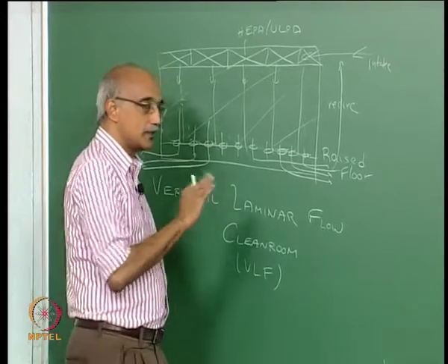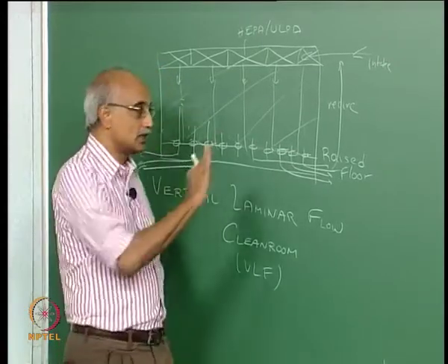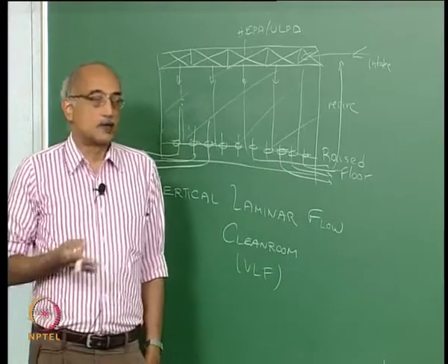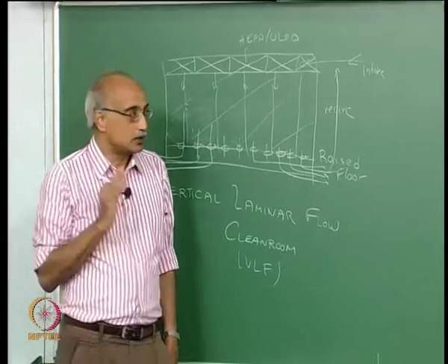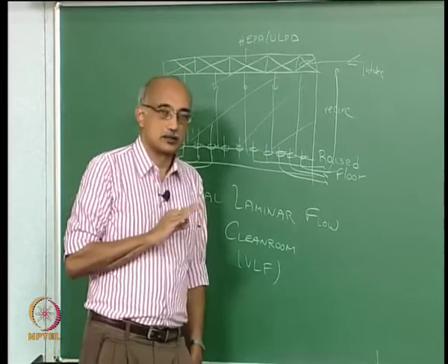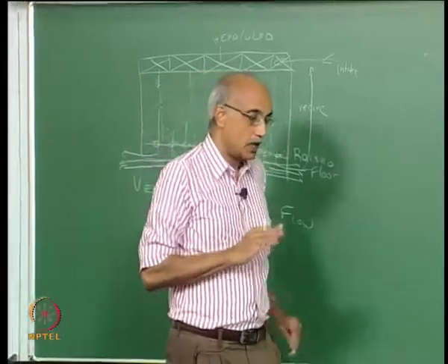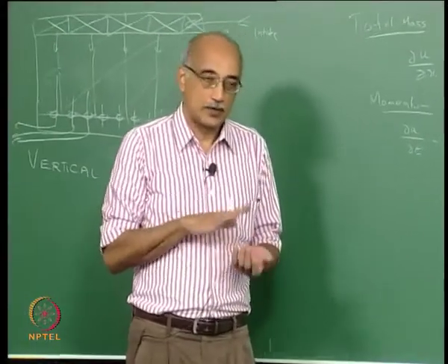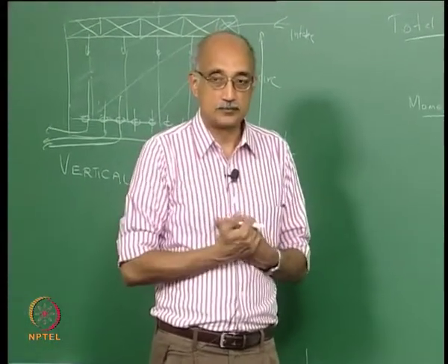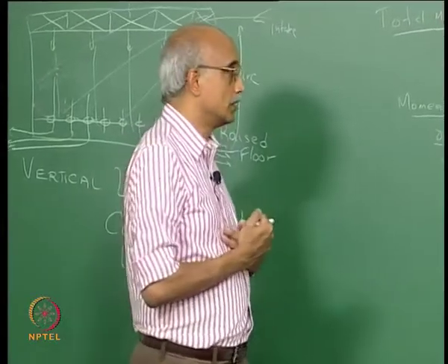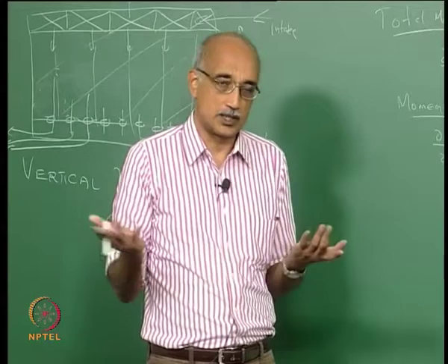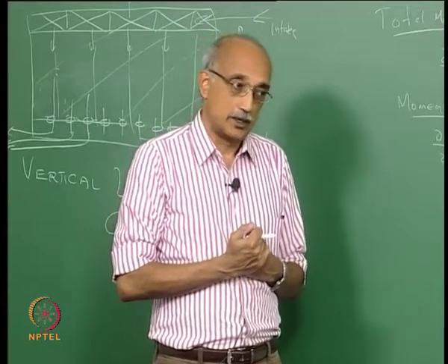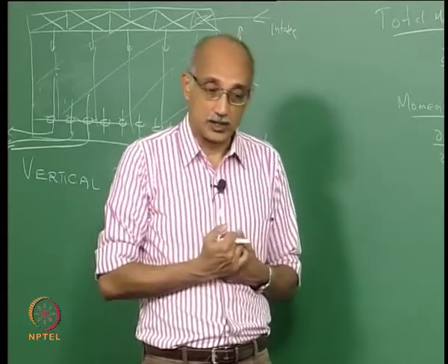So, by applying the appropriate initial and boundary conditions, you can essentially set up the model, solve it numerically using finite difference approximation, and you can actually get a very precise description of how the flow field will look, the velocity distribution, and you can also predict how the particle concentration distribution will look inside the clean room. And in fact, we have done that exercise in our lab.